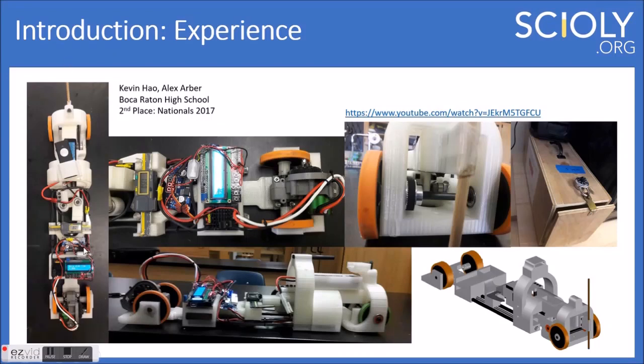You can see the caliper that we use here for doing the steering. So we set up a linkage system, as you can see. This caliper, we cut off part of it just to make sure it would fit in this smaller area, and we didn't really need the full length of the caliper. Obviously, very small increments of the caliper resulted in huge changes with the angle. We really only varied it by a couple millimeters, I think, at the end. It really wasn't necessary to have a large movement there.